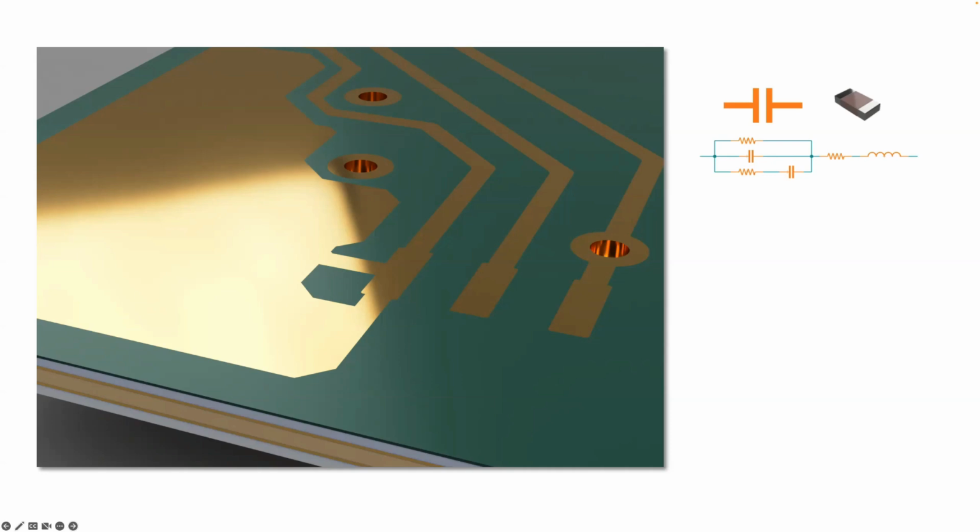And instead, you do have in that capacitor model a whole host of things that maybe you didn't know about: insulation resistance, the equivalent series resistance of the capacitor, the series inductance on the leads, or lead inductance, and the plates themselves have an inductive property. You've got dielectric absorption. All of those are characteristics of a capacitor that, in a highly simplified view of a circuit, give an outcome that looks idealized. And that's oftentimes what you get from SPICE simulation.